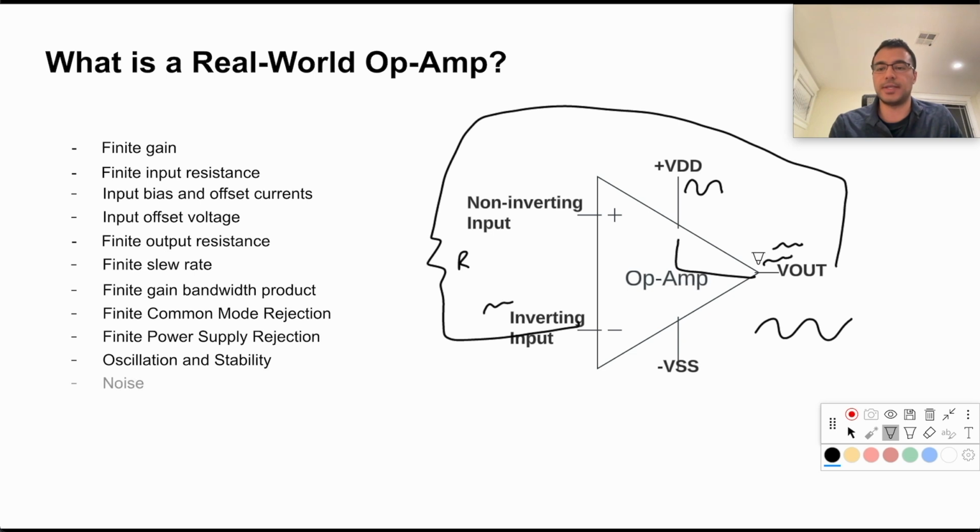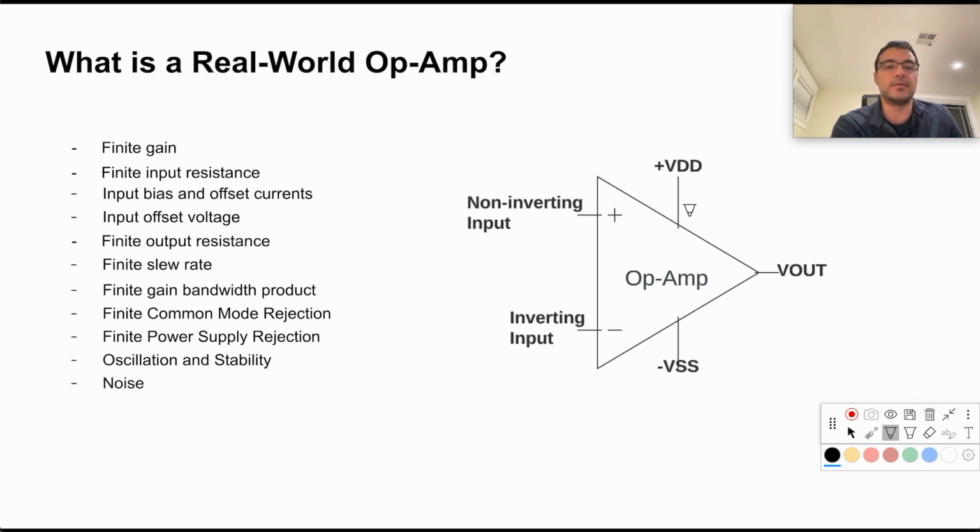That's just one example. An op amp internally also has some amount of noise. This could be thermal noise or other types of noise, where it itself will add some amount of noise to your signal. Even if you give it perfectly clean signals, both for power and input, the op amp itself might add some noise to the output. The op amp is also extremely sensitive to temperature effects, just like a normal transistor is.